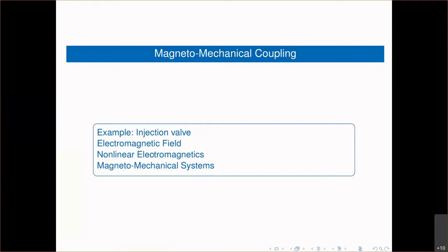the relation between B, the magnetic flux density, and H, the magnetic field intensity. I will provide you a general framework via Fréchet derivatives, how you can derive a Newton formulation for a nonlinear partial differential equation, and clearly we will use the partial differential equation of the magnetic vector potential describing the eddy current case of electromagnetics.